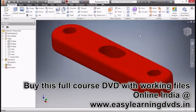I can't stress enough how creating good relationships inside of an Inventor model is key to working effectively in this type of software. If you have designs that change in an expected manner, everything is going to update more effectively, and you'll have fewer problems trying to repair geometry that was not created in an effective manner.